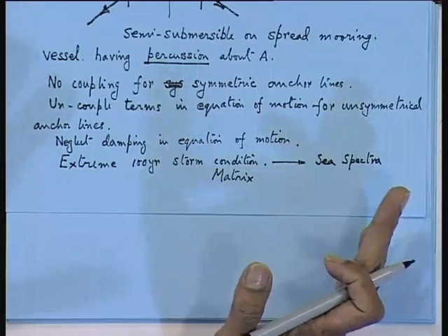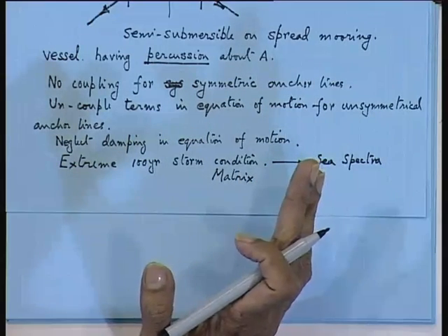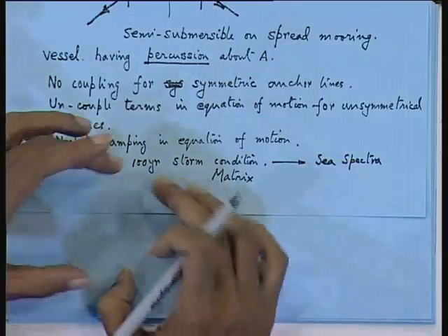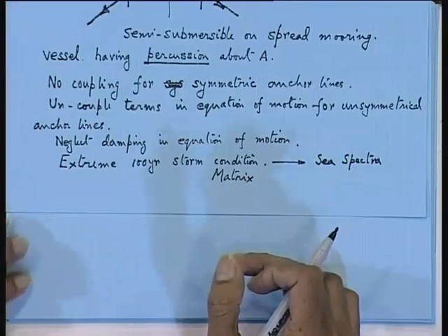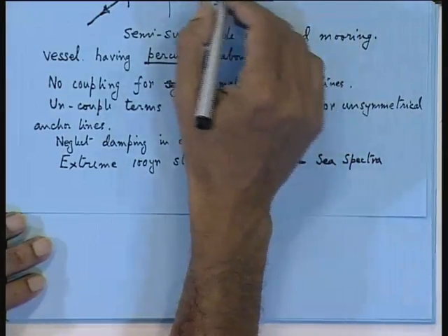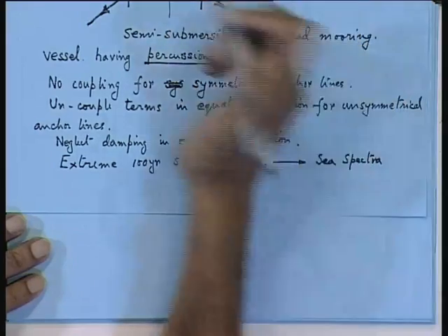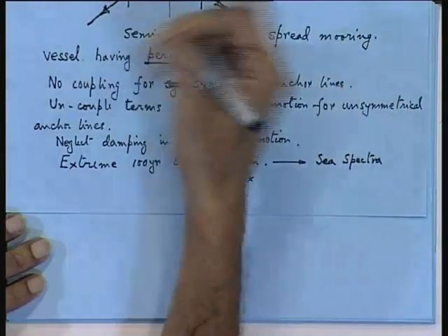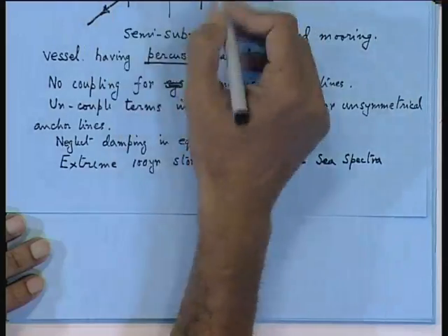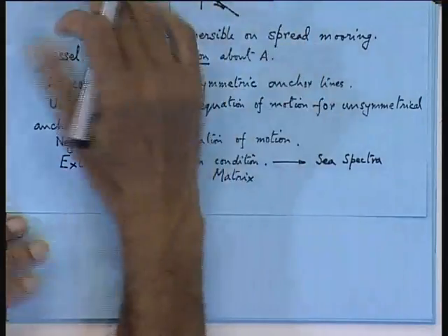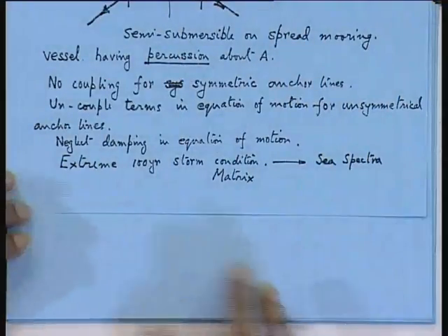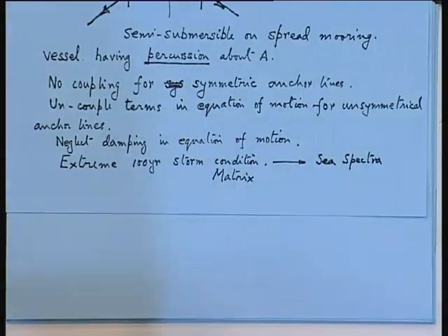Next you have the 25-year storm criteria, 50-year storm. Like this you have to generate a matrix, with say one anchor line snap, say two anchor line snaps. You do the calculation, say in Orcaflex, with say 4 anchor lines, 6 anchor lines, 8 anchor lines, and all this. So you have to generate the design data, or a design matrix has to be generated with a number of